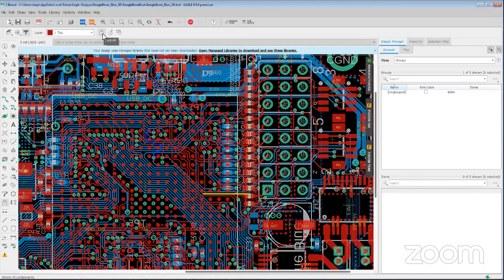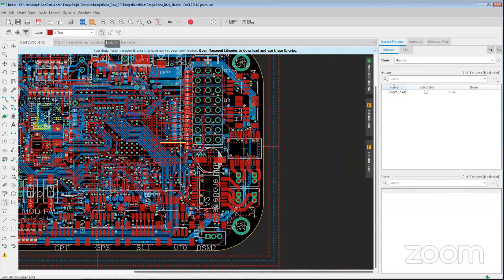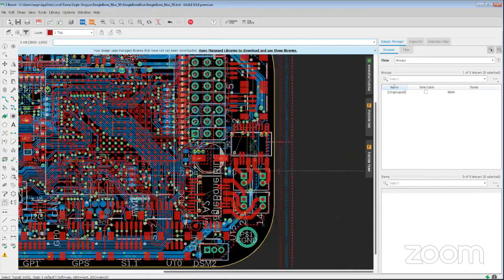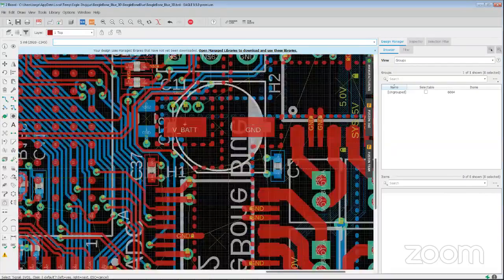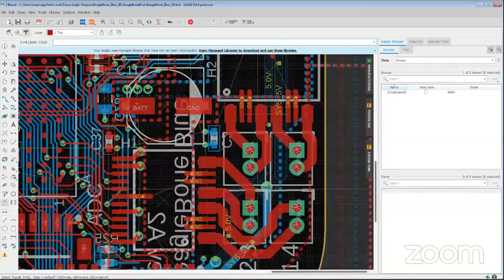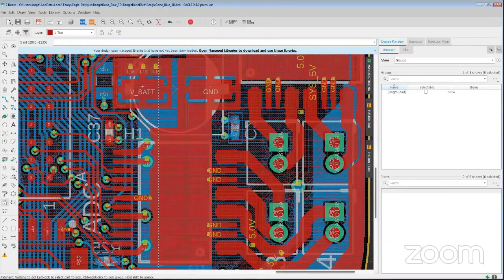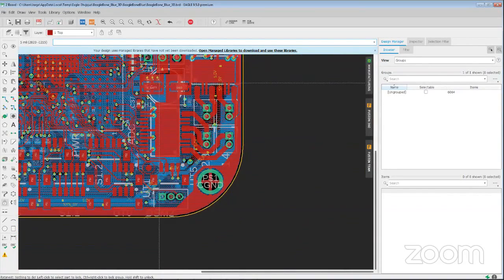You can just choose to lock everything, and this basically is going to avoid confusion in case somebody's looking at your design and wants to inspect something and you really want to make sure they don't move anything. You can just lock the whole thing, as you can see here. At this point, nothing becomes movable, anything that's already there. Obviously, if there's air wires and new traces and things like that, then those wouldn't be affected. But anything that's already existing basically gets locked and can't be modified.